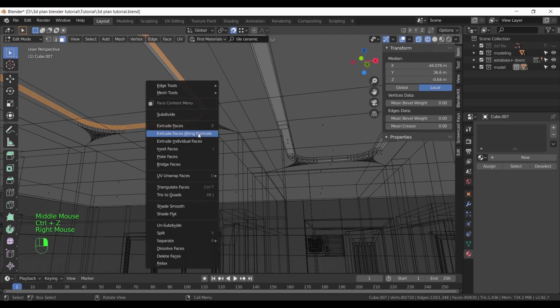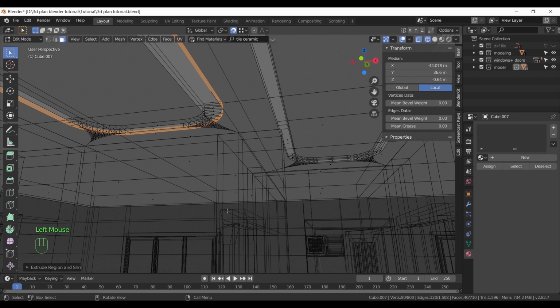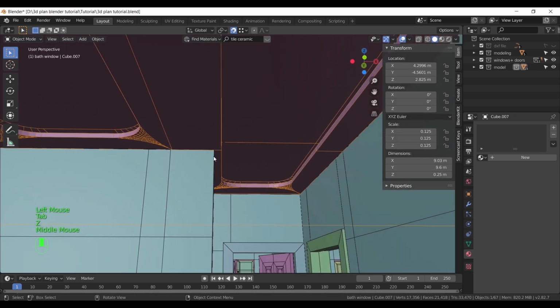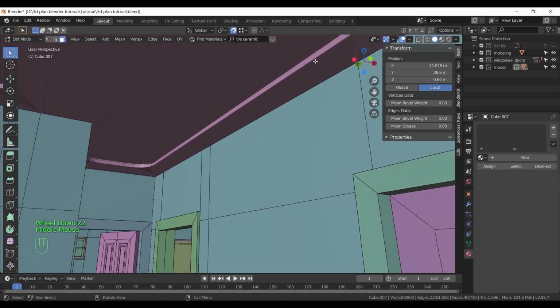Now normally, we could just give those faces we pushed inside a light material, but with Eevee, the emission won't work unless you're looking at the area. So if you are working with Cycles, add to it an emission light material, that will do it.